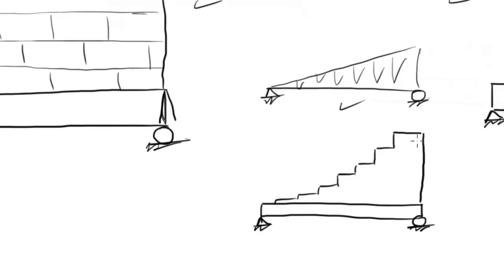Okay, so the masonry wall is not completed yet. For some reason the guys at the construction site stopped constructing the wall, so the best way to stop it is by creating an angle of 45 degrees like this one. So the load created by this unfinished masonry wall will look triangular like this one.